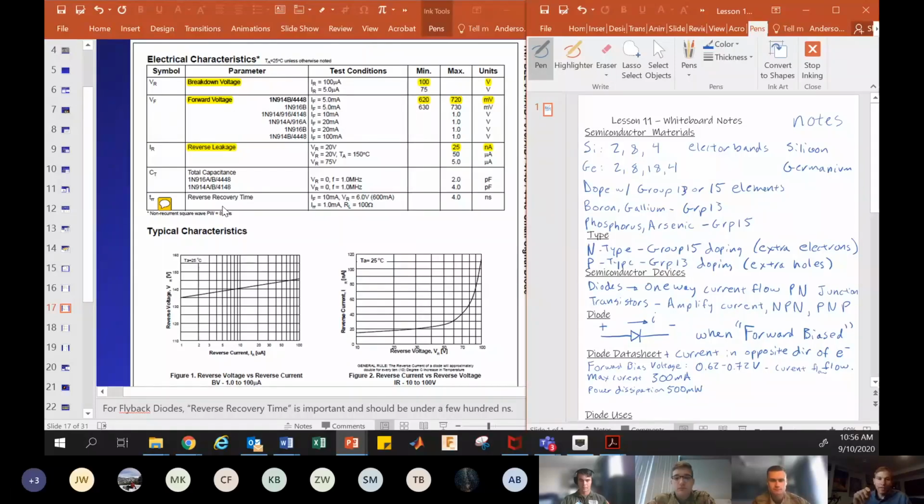We saw this in the lab when we were looking at the oscilloscopes, how your plots were going down to the 2 volts, and then we switched from input mode to output mode, and it dips down really quick and then goes back up. It may be that there's a diode in there that's being switched, and the current's being switched, and that reverse recovery time is allowing some current to flow in the wrong direction. That could be what's happening.